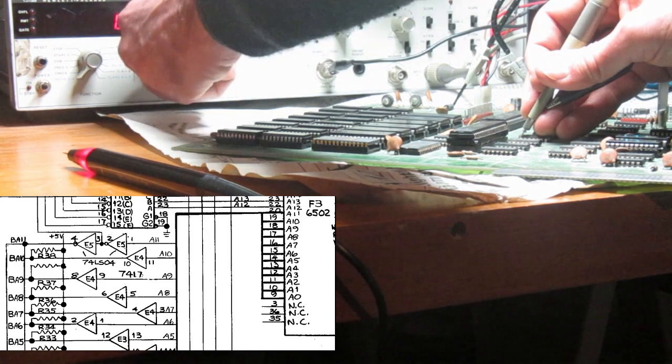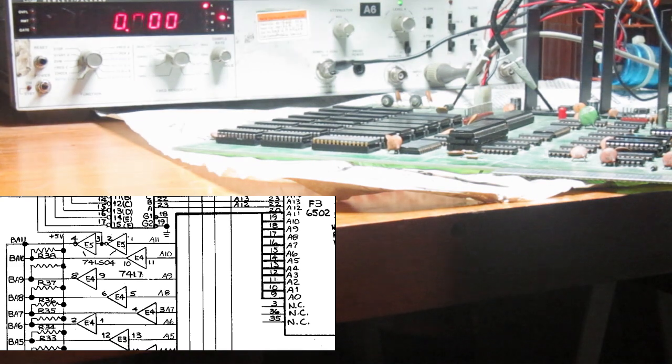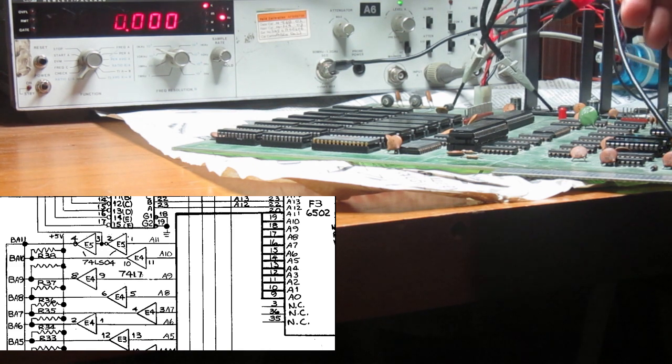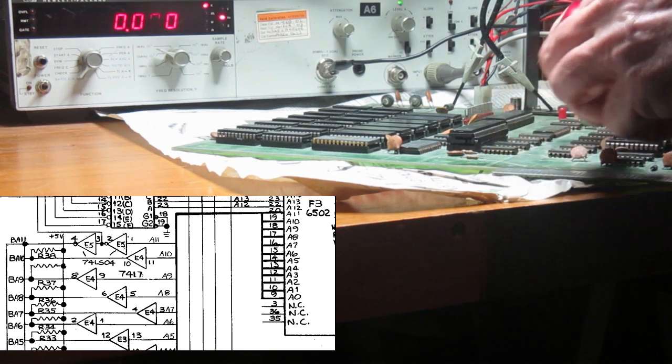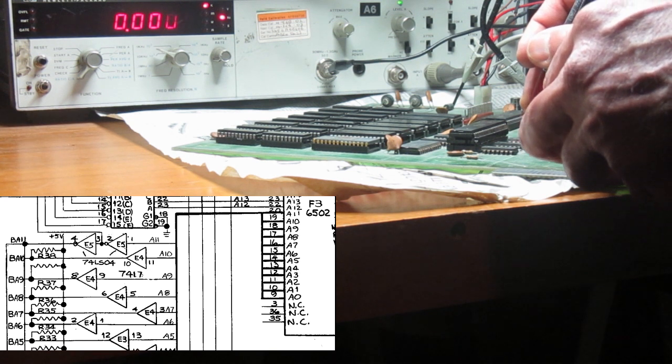This is too slow. Maybe we check that with the logic probe instead, which is faster. We just want to know if the addresses are toggling and the buffer working.